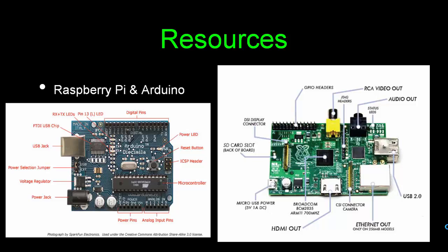The difference with the Raspberry Pi is it's a complete microprocessor as well. It's an onboard computer. So you can use keyboards, mice, USB products, and HDMI output. It has many general purpose I/O outputs, more than the Arduino does. And it has add-on boards and add-on shields to actually have A to D conversion, PWM.